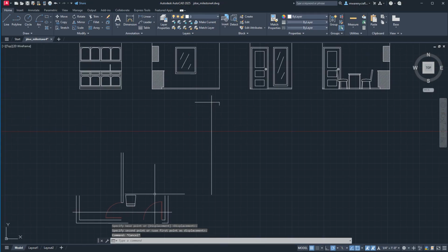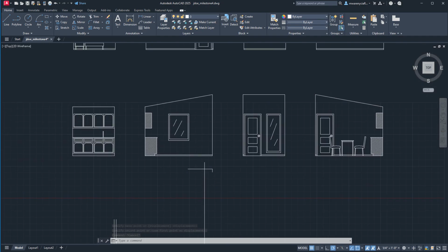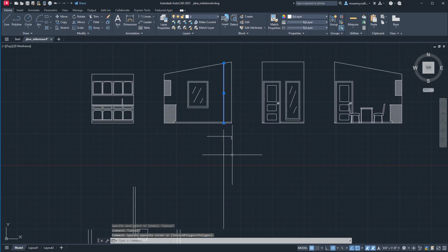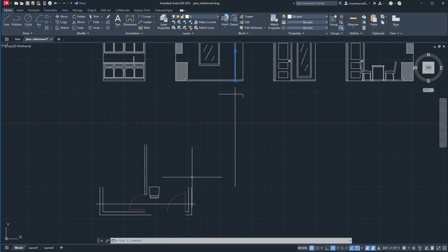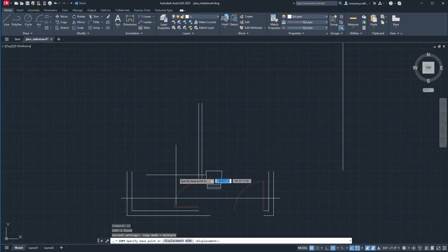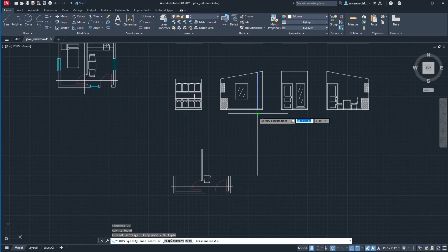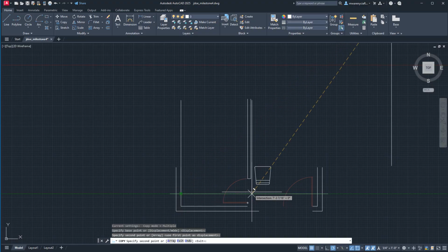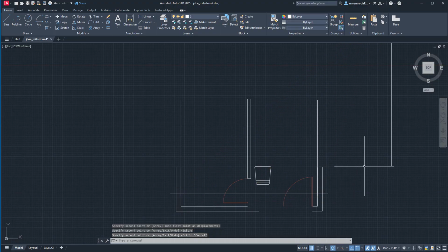And then I'm going to move this so that this angle matches here. So what I've effectively done here is I know that my section cut goes through this space. I know this distance right here, so I'm moving it so I can get this distance right here, which is going to tell me what my height is right here. So this right here is the height for this section cut based on this gap from here in this corner. So this is going to be my section cut height. So what I'm going to do is I'll place this there and there.